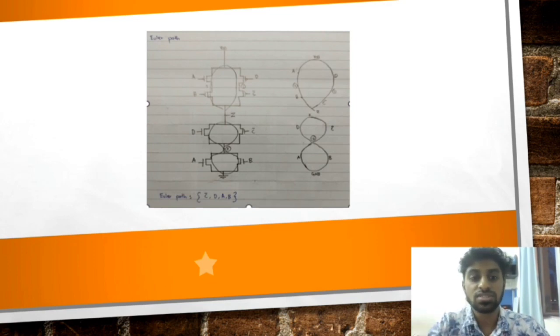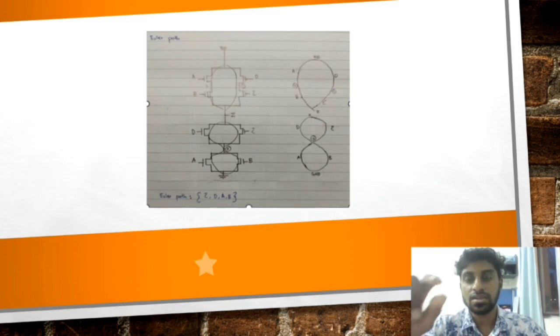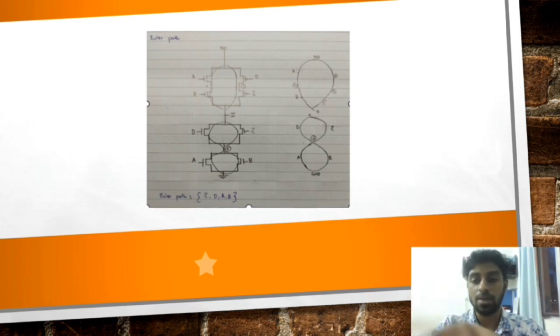There are certain rules when it comes to constructing a Euler path. The path should be defined by the order of the transistor name for each of the inputs. The names of the inputs can be alphabetical like A, B, C, D, or it could be D, B, C, A, or it can also be 1, 2, 3, 4, or anything. It is also important to construct it in such a way that there is only one variation for the pull-up network and the pull-down network.